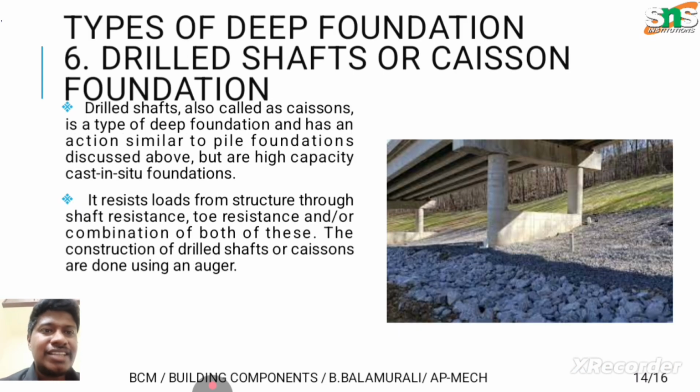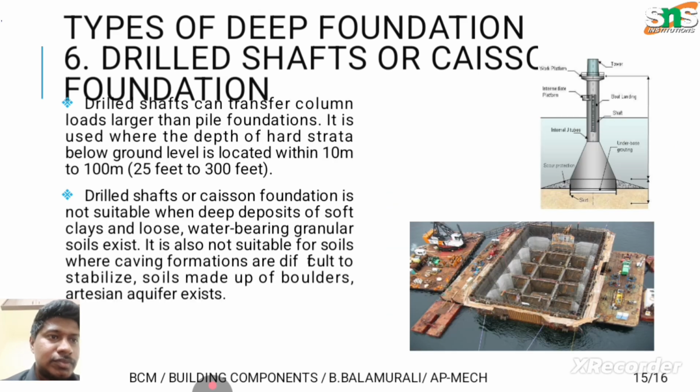The final one is the drilled shaft foundation, which is probably used for building national highways and bridges, and in uneven soil areas. It resists loads from the structure through shaft resistance, toe resistance, and a combination of both. The construction of drilled shafts is done using an auger. It can be located from ground level within 10 meters to 100 meters, that is from 25 feet to 300 feet of ground level.